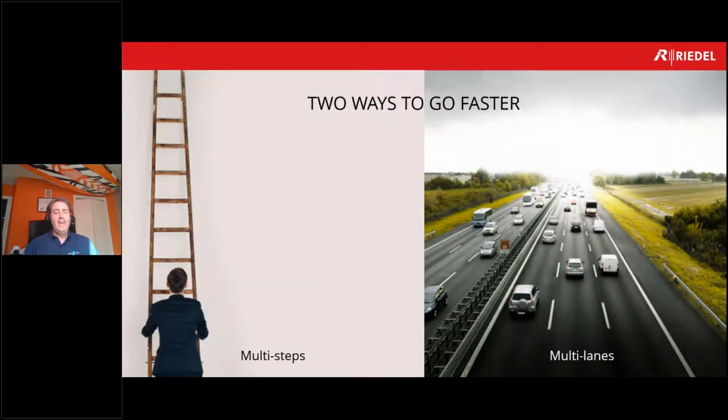So here is how to do it. It's really interesting. One is multiple lanes, like multiple coax, you will tell me, or like multiple fibers, and you're totally right. And the other one that is really cool is multiple steps. Think about your ladder as a bit interval or a symbol or just a unit of time. And then you put multiple steps. Instead of being 0 and 1, it's now 00, 01, 10, 11. And you have 2 bits per ladder step.